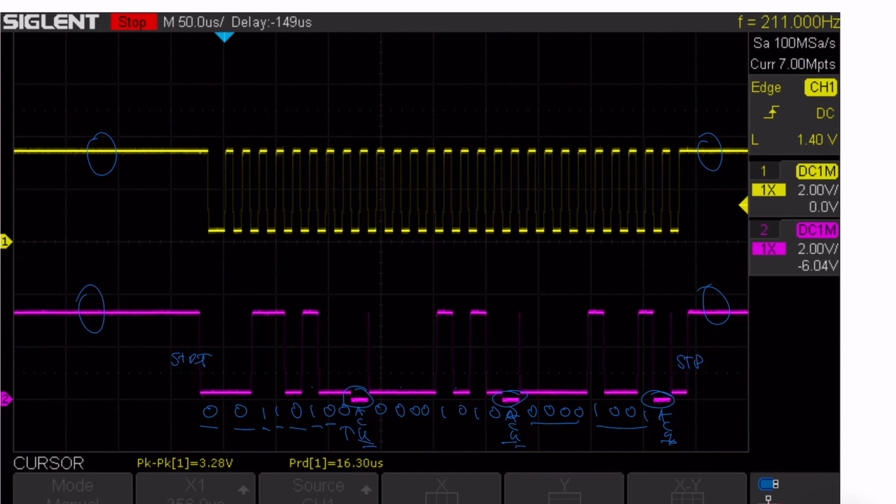So we saw those 8 bits there. We saw an acknowledgement. This here is the register on that slave. So it's 00001010, and then after those 8 bits, we see another acknowledgement. After that, maybe this is a data value, 00010001, and then another acknowledgement, and then our stop condition.